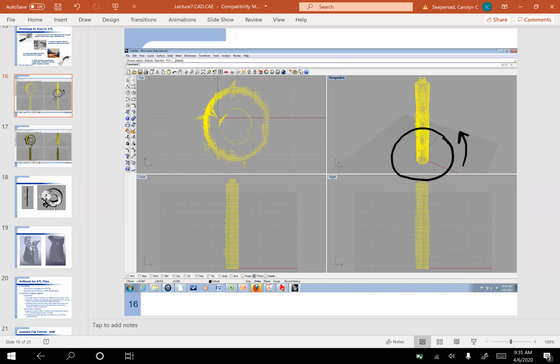And then off to the side, it has a laser scanner, all right? That laser scanner stays fixed, but it moves up and down, okay? And as it does that, it basically shines a laser light onto the object and looks at the time of flight. And based on that, it can tell how far away that geometry is. And it generates what's called a point cloud of data.